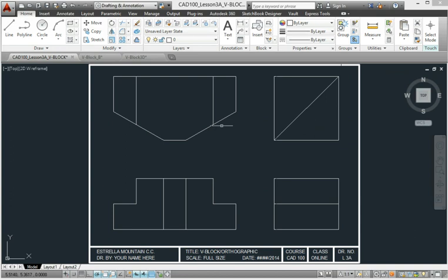Now to transfer information from the top view to the right side view and from the right side view to the top view using the miter line. This is the process. Polar tracking sometimes helps with this, and we'll see if it does. Click the line command, grab this corner of this feature. Yes, it does. Let's just grab the intersection of the miter line and the projection line. Pick here and let's extend it down. Perpendicular. Enter, stop the command, enter to repeat the command.